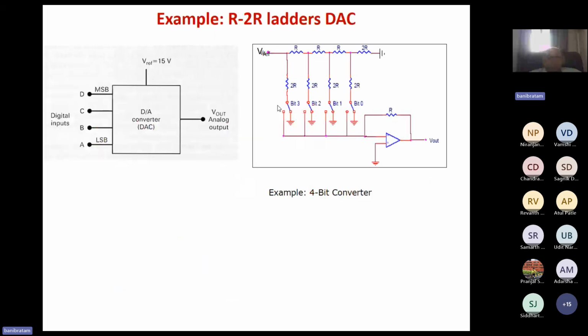After that, we have discussed this DAC example as well, where we talked about the R2R ladder network based DAC, and there we discussed that in this case the V reference is getting affected. Here this is VREF, and we have derived that it will be VREF by 2, VREF by 4, VREF by 8, like that the reference voltage will change, and the current will be passing through the op-amp depending on whether this particular switch is at the 0 position or at the inverting terminal position.